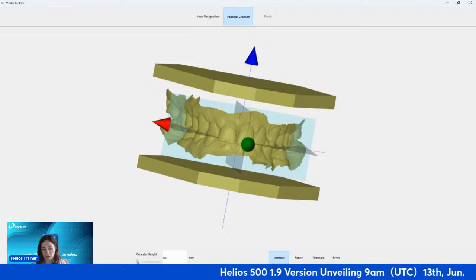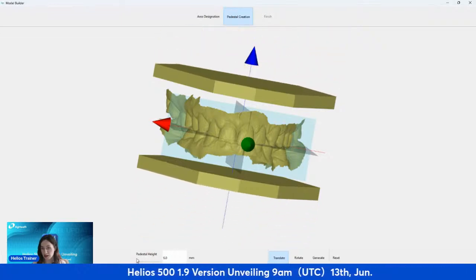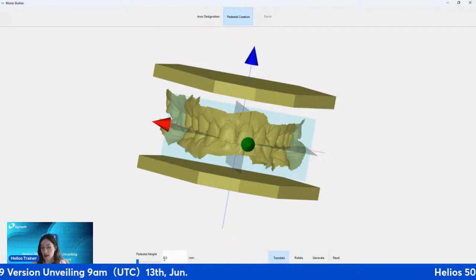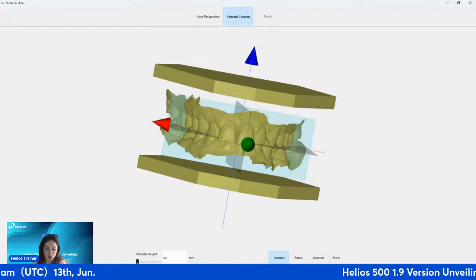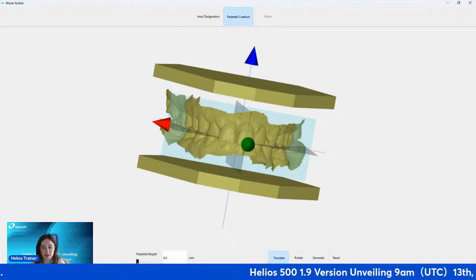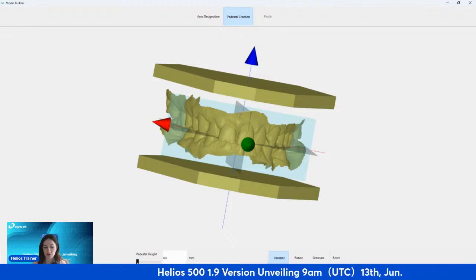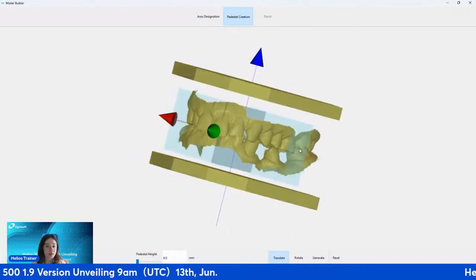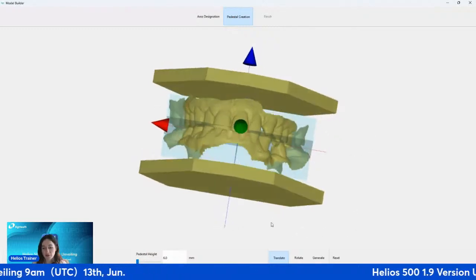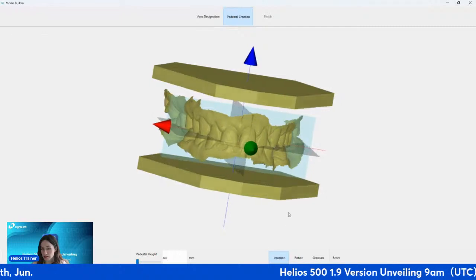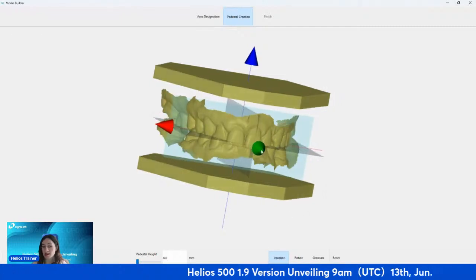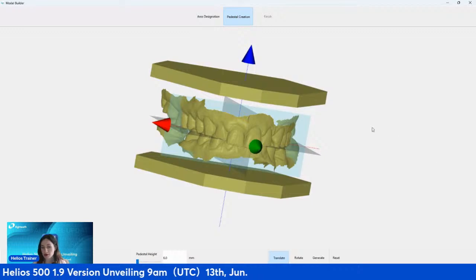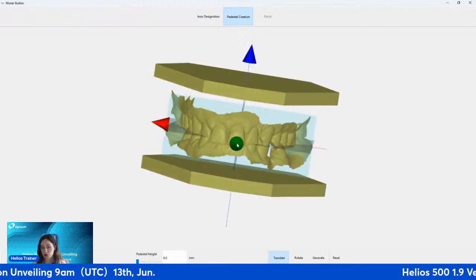And there you will be seeing the pedestal height, that you can adjust the height, how many millimeters you want to have for this. I would prefer to use as much resin as I want to use, so it will be in the lowest millimeters, okay, for me. And now I'm in the translate option, that if I click with my left mouse, you are going to see the model and the base position, it's going to change.